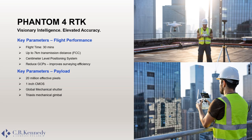So like with the P4 Pro, on a fairly large scale mapping site, you need to put between 8 and 13 GCPs down. With the RTK, you can get away with using 0, although if you want to increase the absolute accuracy of the data set, then it's recommended to put around 5 down, but still that's quite a significant time saving. All this data is actually captured through the 20 megapixel 1-inch CMOS sensor, and it has a global mechanical shutter. So all this is combined together with DJI's new time sync system, which I'll talk about in a sec.